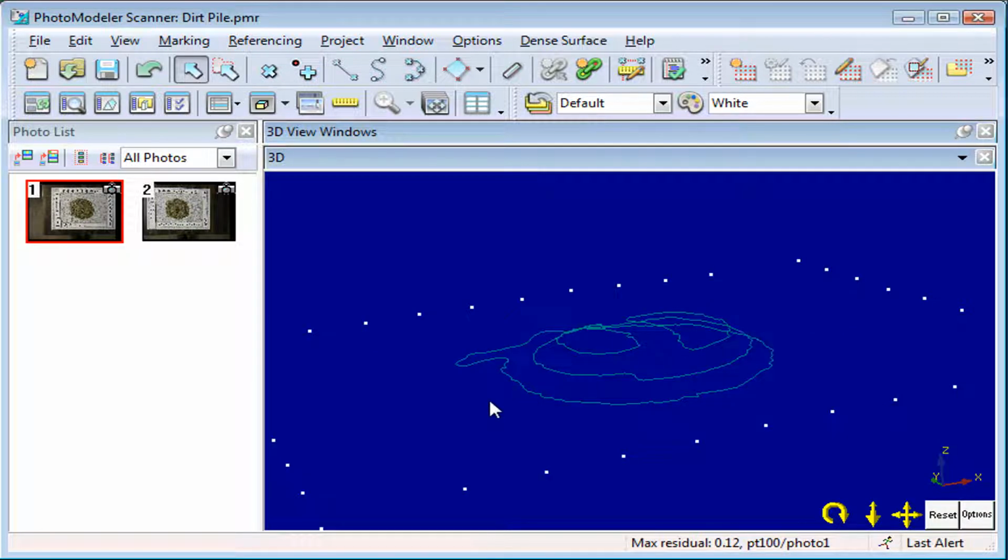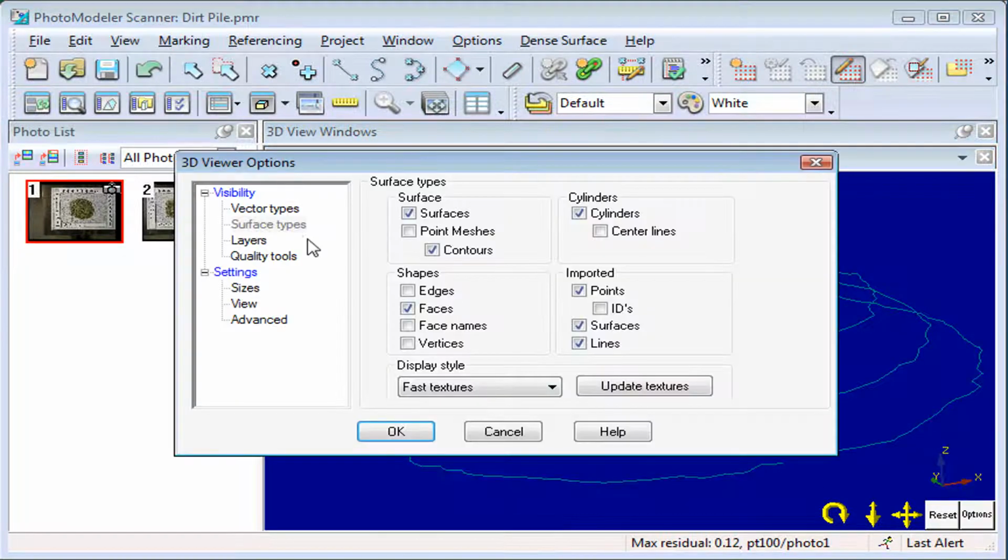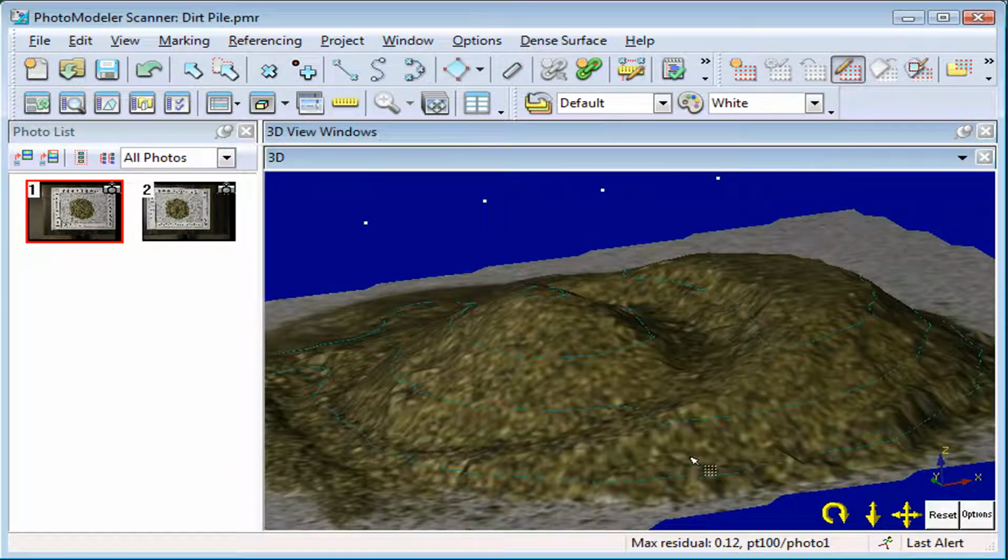To remove an individual contour, you can select it and press Delete. Undo will bring the contour back. In Point Mesh Edit mode, you can select individual segments of an existing contour and remove them by pressing the Delete key. This can be useful if you do not want the contour to be a closed loop. Lastly, you can select an individual point mesh and export its contours.